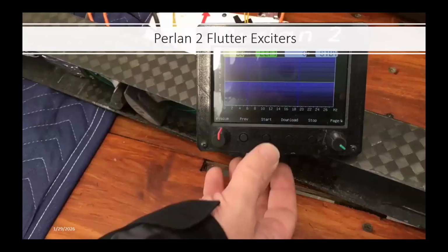So part of what they did is they put some exciters in the structure so that they could excite the aircraft in the air at reduced air densities, in order to validate the equations that they used in their design software. So they put vibrating wings in the wingtip spar. They had accelerometers in the wing. The small monitor that you see on the screen, the horizontal axis is the frequency of the disturbance. So that looks like it goes anywhere from 0 hertz up to about 27 or 28 hertz or cycles per second, depending on how you like to hear that term.